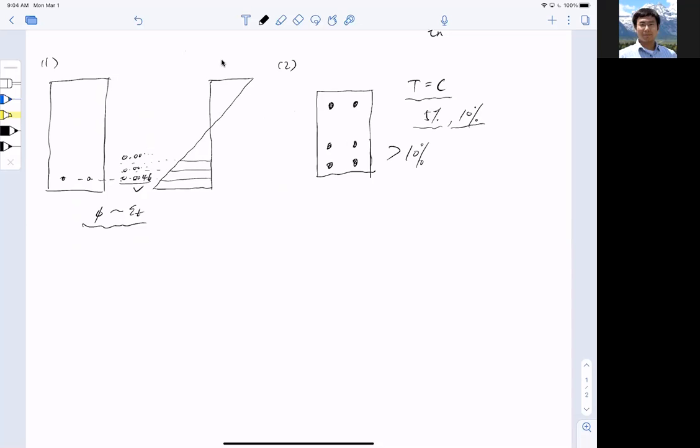Okay. Now coming back to this problem, you need to make sure that the compression and tension are balanced. All right. So the other question is that some of you may say, look, Bob, I know they're not balanced, but I don't know which direction I should move towards. Should I increase the compression zone or should I decrease the compression zone? It's a very simple rule, right? You think of it, the tension equals the area of reinforcement AS multiplied by the yield strength of steel Fy. So when your AS is fixed, as in problem number 2, which is the case, your tension force is kind of fixed normally, right?